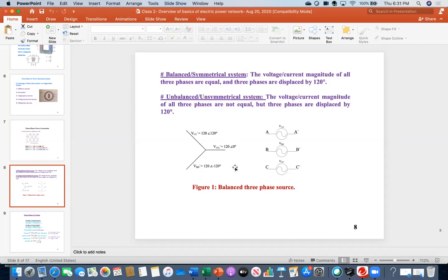there could be. For example, you have a three-phase system, and at the beginning of the installation, all three phases have equal impedance. They have equal inductance and equal resistance. But over time, for example, one phase has much more impurity, some corrosion or some sort of dirty thing added, and that changed its resistance. Or a coil got a little bit damaged. That set of coil will have different impedance than the other two.